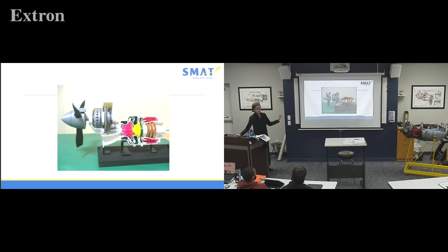Questions on kind of how that all works? Where does the diffuser stop? Where does the combustor start? So air's coming up, so they have it color coded, like, well, the diffuser should be like right in here. They didn't make that real obvious, but then, like our reverse flow on the PT6, the air is wrapping around and going in all these perforations for burns.